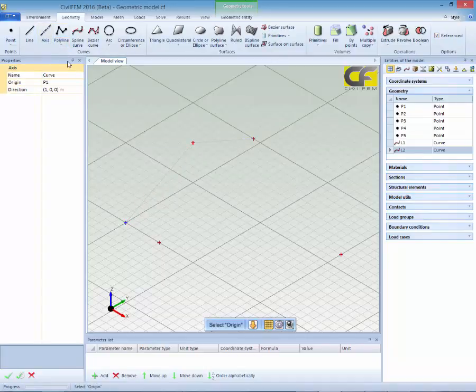We have the axis because sometimes when we want to make a volume extruding or making an extrusion from a surface, we have to make a line where the propagation of the volume is going to be. Okay, so we define an axis, but we will be using this tool later or in the next section.